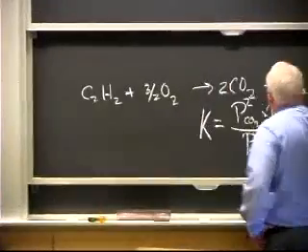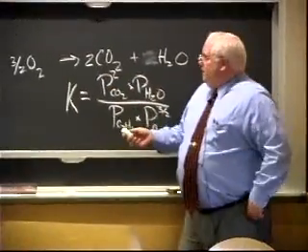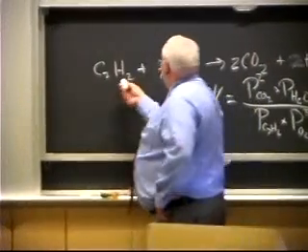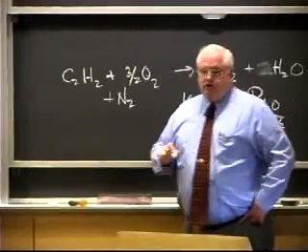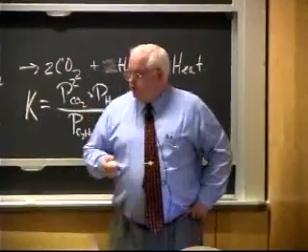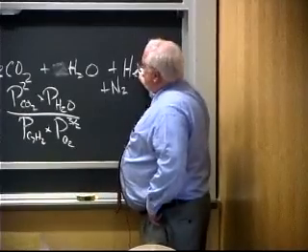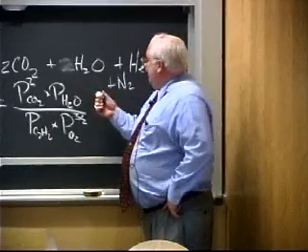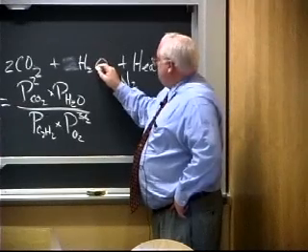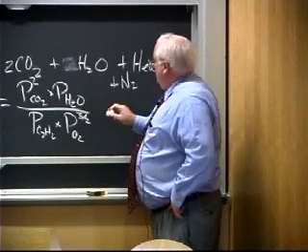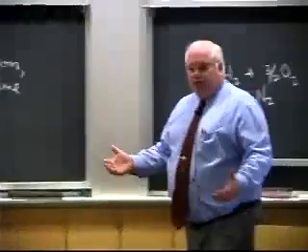And if that heat only has to heat up the products of the reaction, I'm going to get the highest temperature. So if all I've got is fuel and oxygen, that's great. But if I'm burning in air, for every mole of oxygen, I got about 4 moles of nitrogen. And that means that over here, the heat, which is a fixed value, not only has to heat up the carbon monoxide and dioxide, and the water vapor, but it also has to heat the inert nitrogen that's just coming along for the ride.